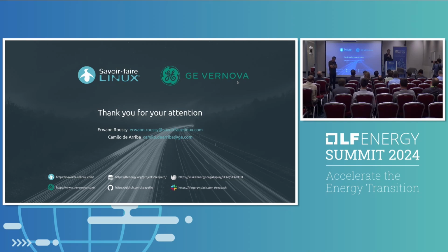The question relies on the end user, the person managing the substation. Is it okay for all the devices in the substation to receive exactly the same GOOSE message two times, or is it not? As I understood, many times it's okay and you don't have any problem because everything works fine, but sometimes it could be not, and we have to think about a way to resolve the problem where it's not possible.